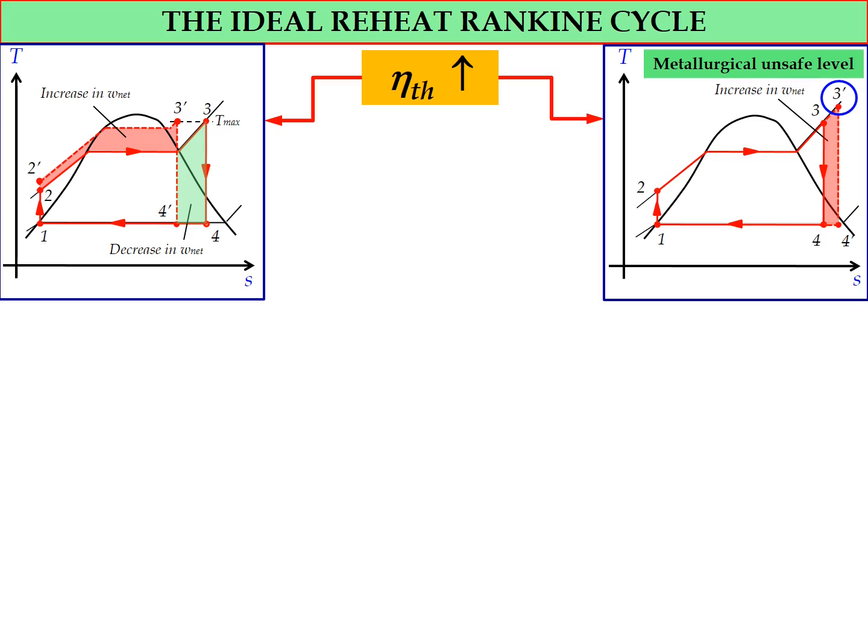is this: in order to solve the problem, we just fix the temperature of T3, okay, and then we increase the pressure at the boiler. However, by using this method, the quality of the steam during the expansion process will reduce, and this condition will cause an increase of moisture content during the expansion process in the turbine. So this also will cause damage to the turbine blade, when the moisture content in terms of water droplets will impinge on the blade surface and damage the turbine blade.